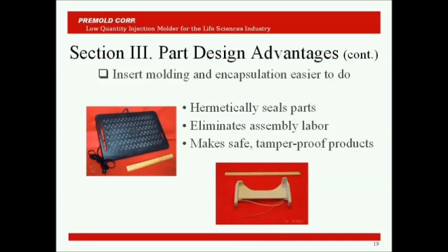The low molding pressures and temperatures in the RIM process make insert molding and encapsulation easier to do. In general, if the parts that you want to encapsulate or insert mold will withstand 50 psi and about 250 degrees Fahrenheit for a brief period of time, and those parts won't be ruined by contact with liquids, because remember the resin is flowing in as a liquid and a chemical reaction turns it into a solid, you can insert mold it with the RIM process.